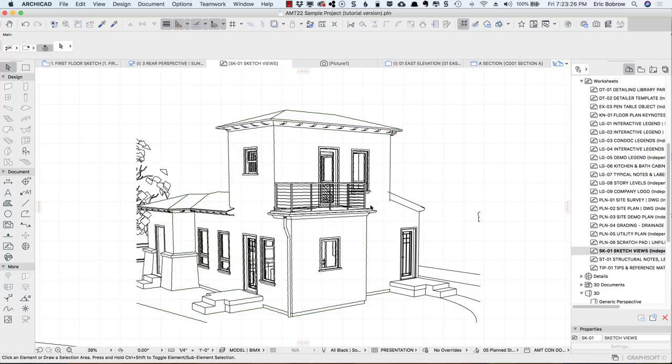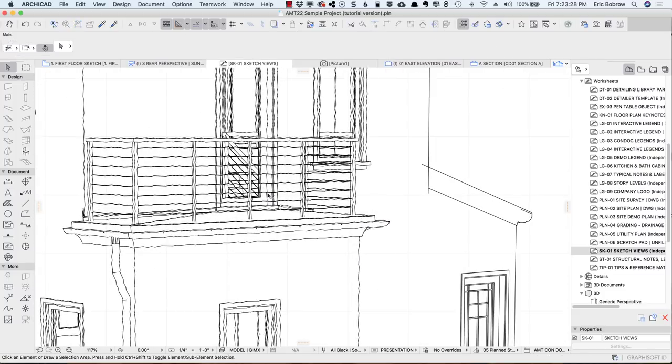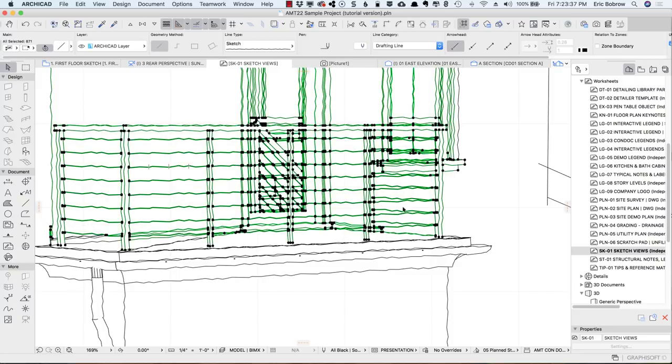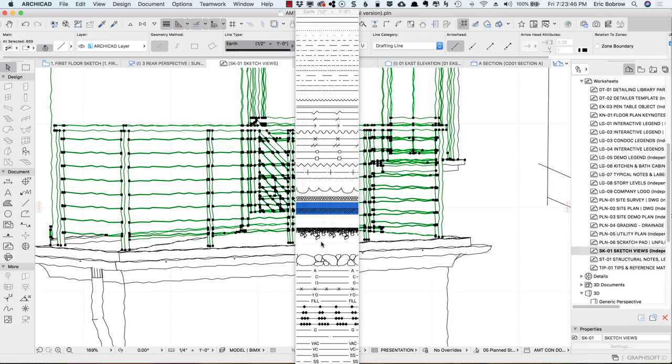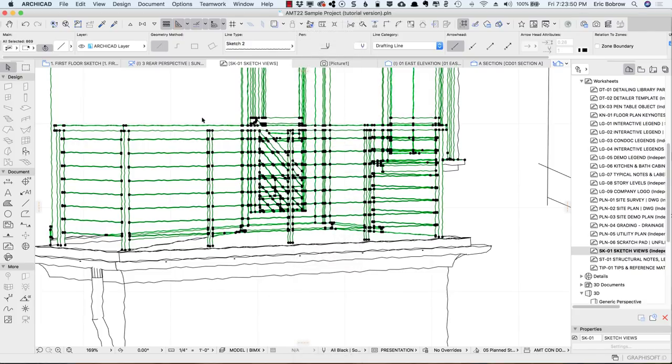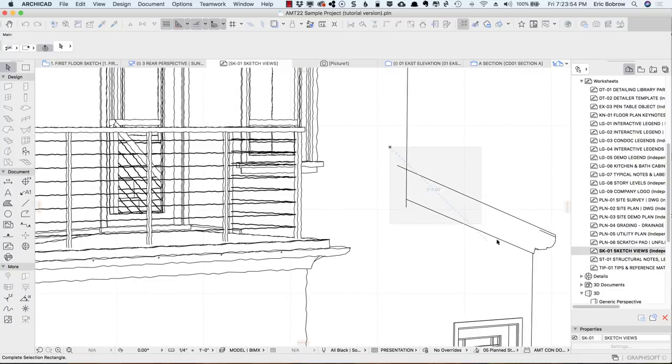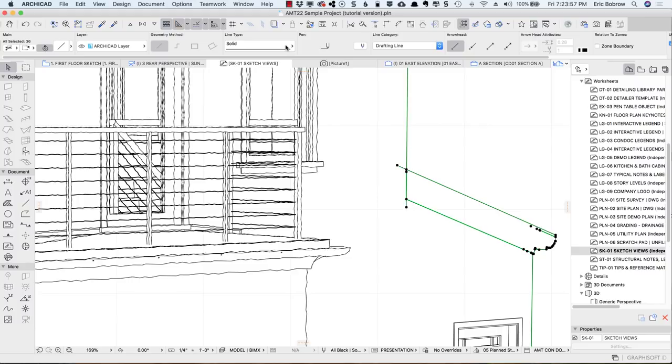And now we can see, if I zoom in on it, that these are sketchy. These are still straight. Now, these ones here, maybe we want to make them less sketchy. So I can select them quickly and, let's not include these guys here, but we can choose them specifically and say, let's choose a different sketch line. Like I have one called Sketch 2. That is a little bit less pronounced. And I also have one here. For demonstration, I'll choose this and make it Sketch 3.